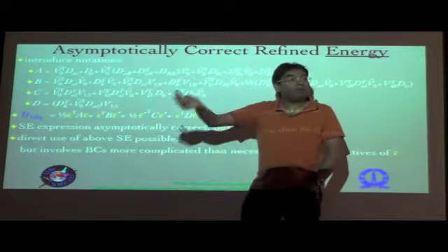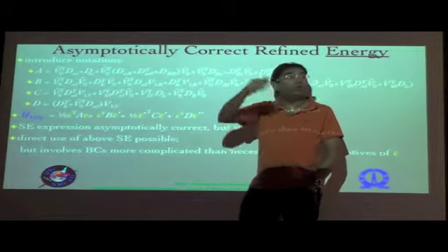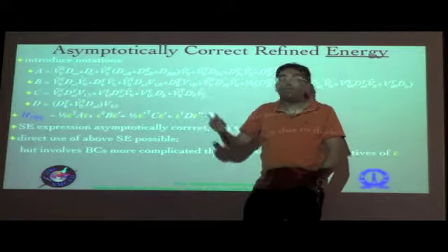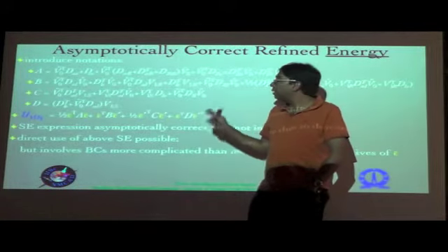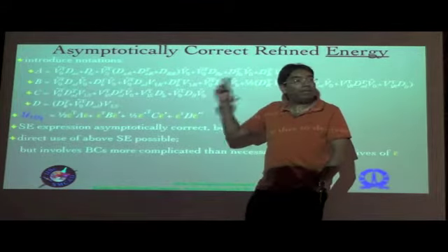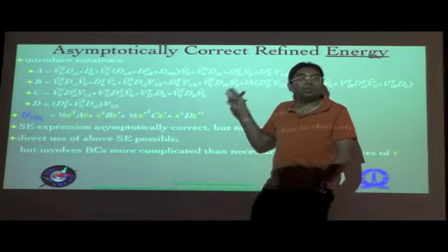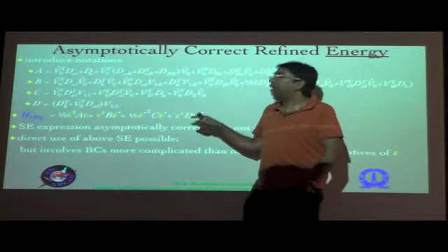So, there are ways of handling that by introducing an appropriate work conjugate for that, what we call the m subscript omega, or the pi moment. Similarly, you can do that in this situation as well, but that's a bit asking too much. And again, as I said, if you want to compare with the literature, the main thing that you can compare with at this level is the Timoshenko theory, and the Timoshenko theory does not involve these primes.